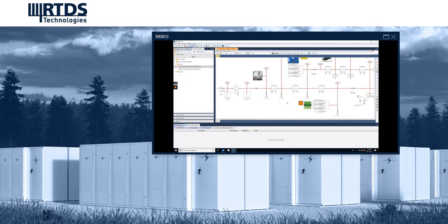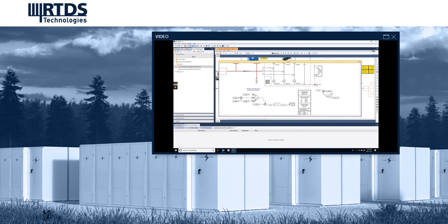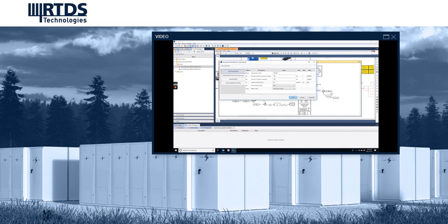The microgrid has 7 loads. There are 4 fixed loads and 3 dynamic loads, representing the changing loads in the microgrid. The battery uses a lithium-ion battery model to represent the charge and discharge operation of the battery in real time. The RTDS battery model allows you to enter the number of cells in stack and the number of parallel stacks to scale the power out of the battery.